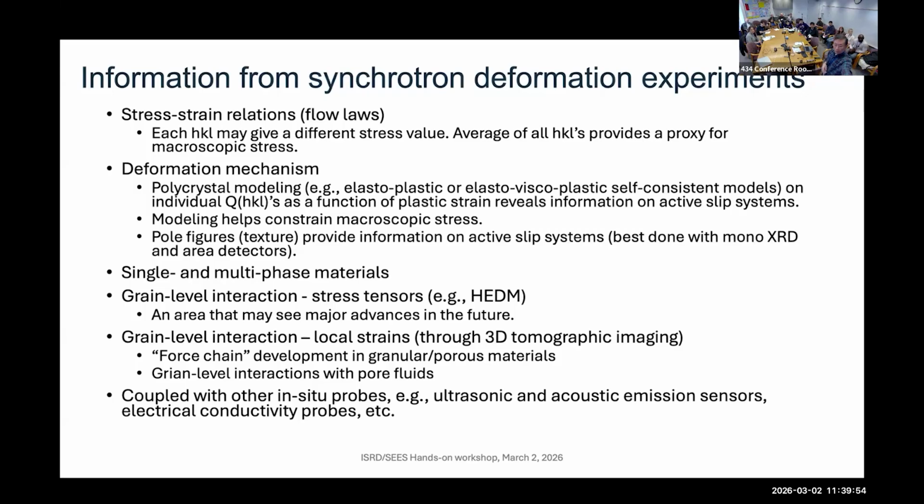The new techniques, like high energy diffraction microscopy, you actually can spin your sample. You collect multi-grain diffraction data as Andy described. And you do this by rotating the sample, and then you can reconstruct the elastic tensors, the stress tensor on each grain if you can resolve these grains. This is a very powerful technique.